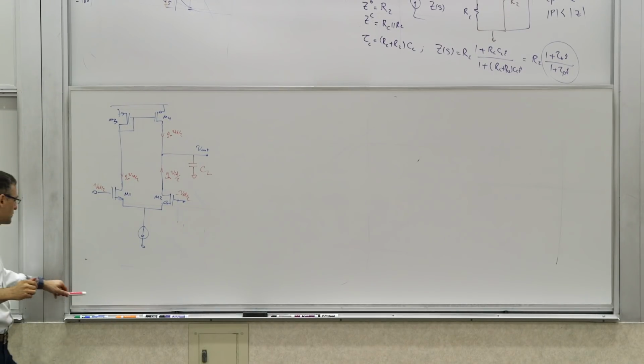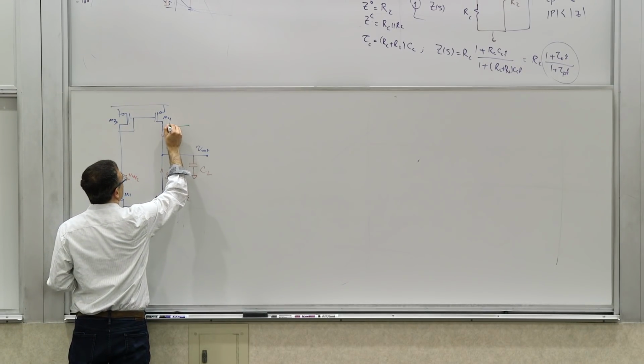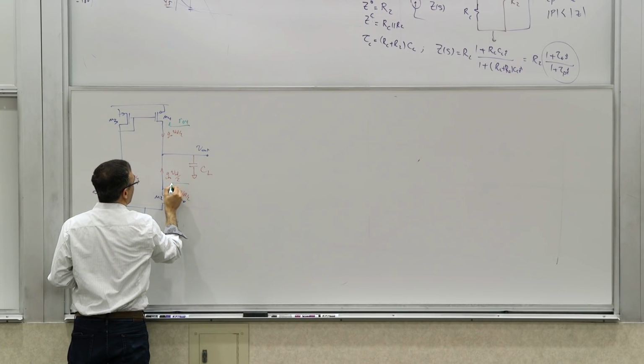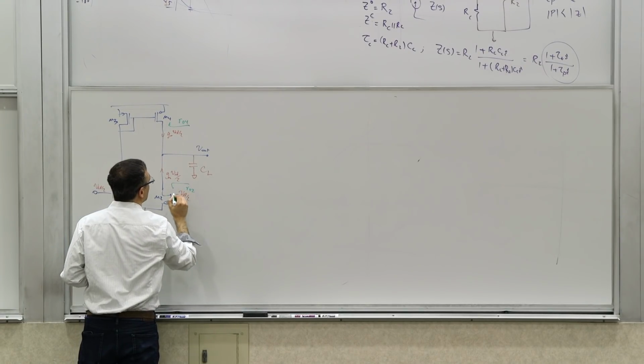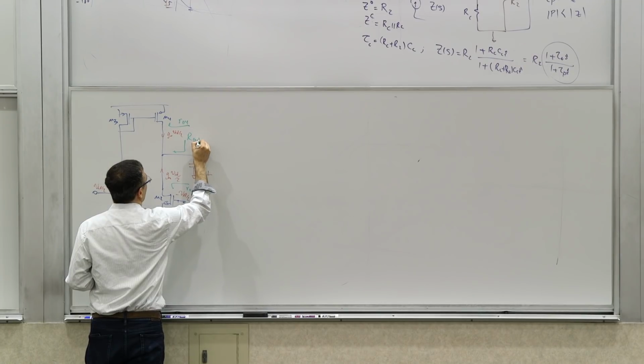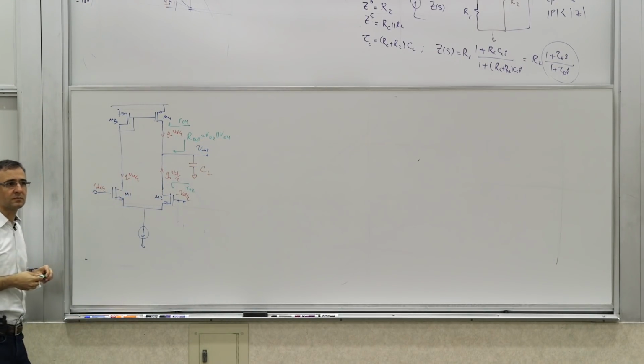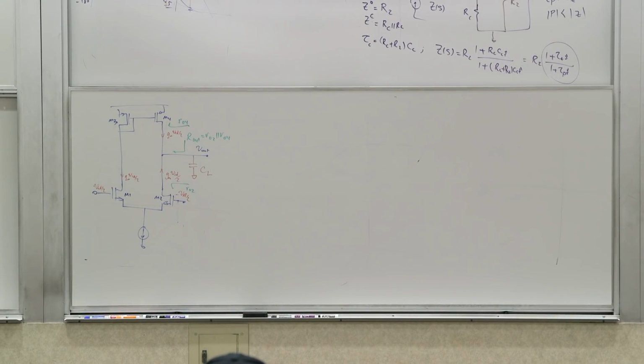These are the kind of calculations we did before, a fair amount of them, right? And the output resistance, what is the total resistance on that node to ground? We've done this before. This was, for example, RO4. Looking down here, you see from a differential perspective, RO2. So the total output resistance, capital R out, is RO2 parallel RO4. These should be familiar calculations to you.